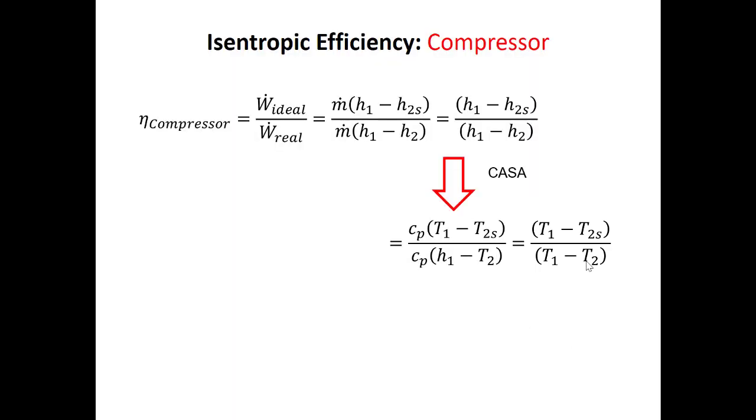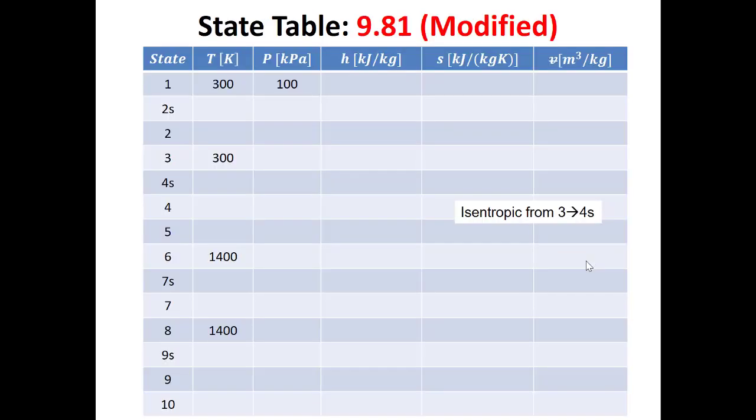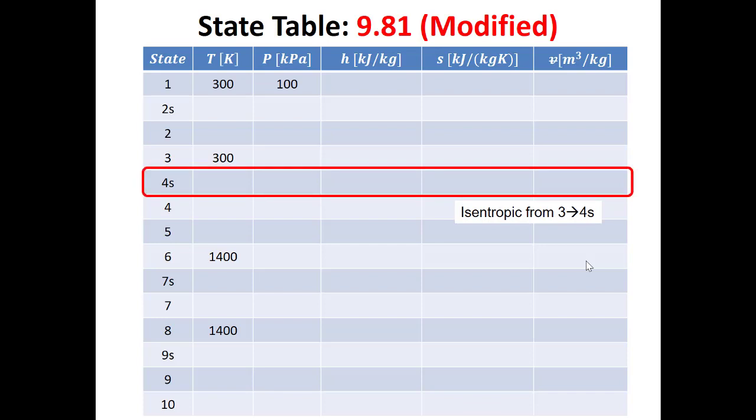So with the isentropic efficiency and the exit from the ideal or isentropic compressor, I can find the exit from the real compressor. So now I've fixed state 2. State 3 I already fixed because they gave me the temperature. And as we move from state 2 to state 3, what happens is we have this intercooling that happens at constant pressure, so P3 is equal to P2.